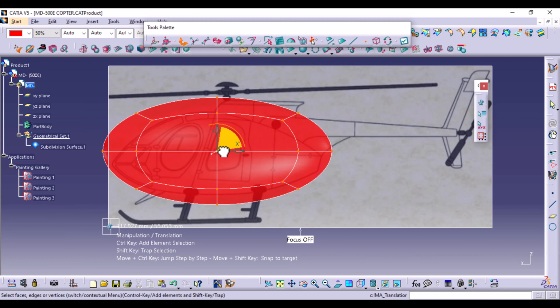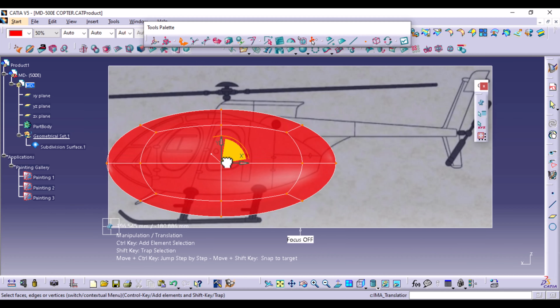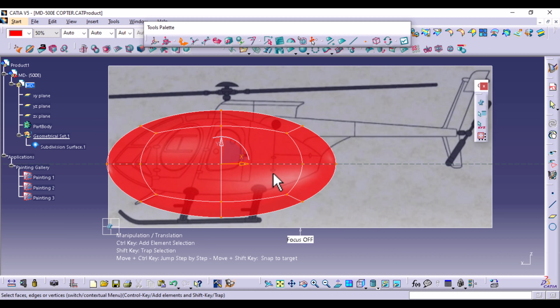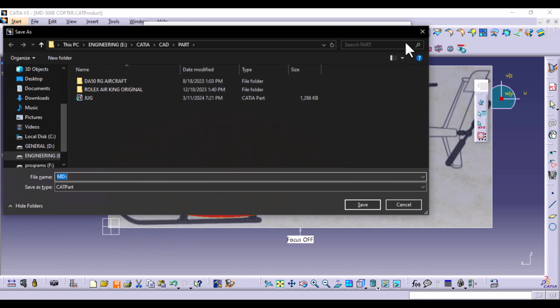So modeling is kind of tedious, unlike in GSD, where you just need to create the specific curves and specific measurements and then generate the lofts or the surfaces. So this is a bit tedious, but you just have to be patient. Any adjustment you make, make sure to click apply. Do this as much as possible so that if you accidentally exit a function, you don't have to go back a couple of steps. And also make sure you're saving your work occasionally.